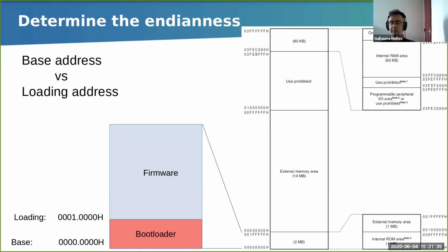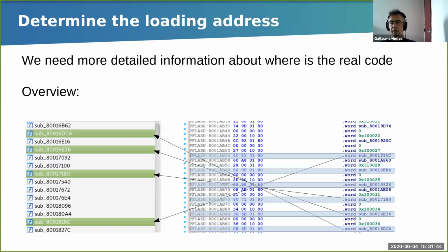No, and it's sad because this is exactly what I want. So what should we do? Basically, in an ideal world, we would know the address of the functions, okay? And if we know the address of each function, we are also able to look for 32-bit values inside arrays inside the firmware, and do a correlation between those two, okay? It's a bit of a chicken and egg problem, because obviously to load the firmware at the correct address, to have this representation at the correct address, you have to know the loading address.